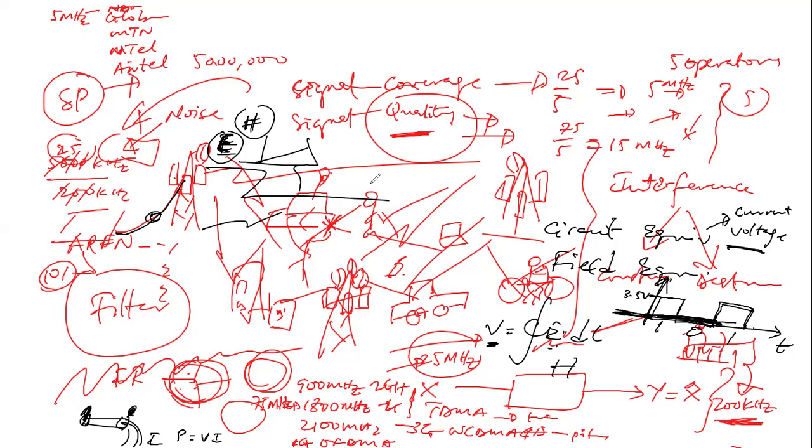We are either dealing with circular polarization or elliptical polarization, where we deal with both the vertical and the horizontal planes of polarization put together, in case it tilts in space. In case the orientation changes in space, and my expected E field, which is supposed to be horizontal, now goes vertical, I will still be able to trap it with my elliptically or circularly polarized antenna. That's why most of your waveguides are designed as horizontal, circular or elliptically polarized. You get that, right?